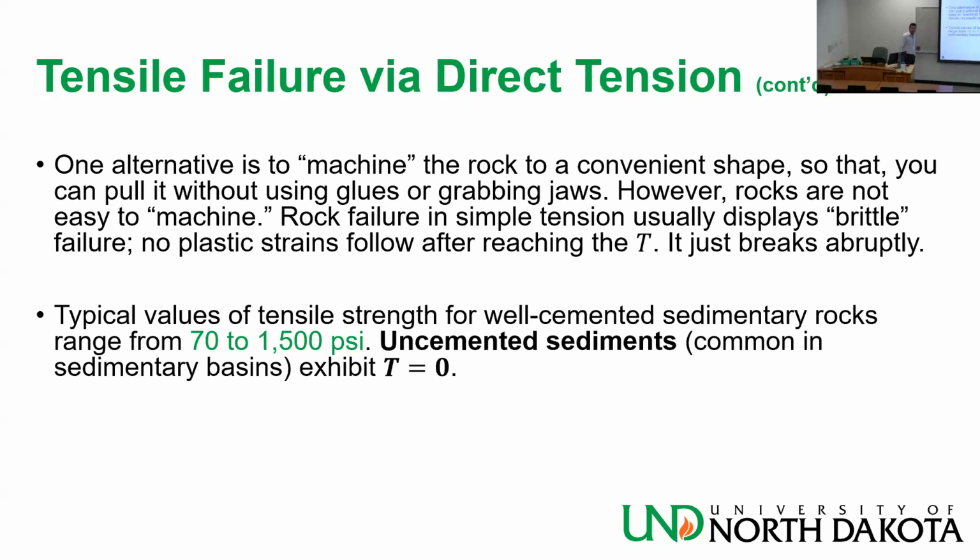So in the far field, T equals sigma 3, because I don't have the presence of a well or interference from other stuff. So this is tensile failure: T is how much strength I need to do this tensile failure. So in the far field it's sigma 3, everywhere is sigma 3, but in the wellbore it's something else.